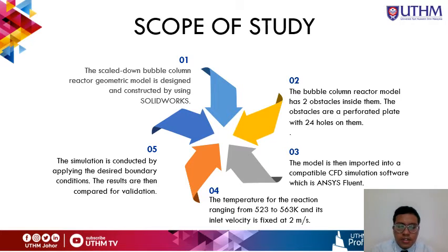The temperature for the reaction is set at 523 to 563 Kelvin, and the inlet velocity is fixed at 2 meters per second. The simulation is conducted by applying the desired boundary conditions. The results are then compared for the aim of validation.